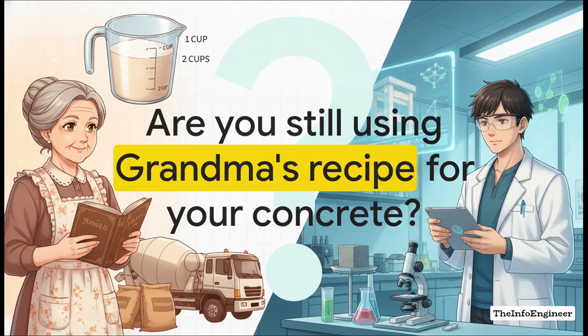But a traditional baking recipe that just says 1 cup of sugar, 2 cups of flour, it's completely fixed. It's volumetric. It completely ignores the fact that today's flour might behave totally differently than the flour from 50 years ago. And honestly, that is exactly what the traditional 1-2-4 nominal mix approach is like out on the site. Today, we're contrasting that familiar, fixed-volume habit against the lab-tested, pinpoint precision of a master chef. We're talking about the design mix.